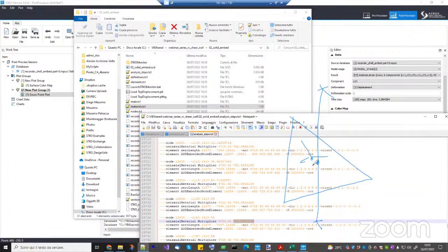Then I take this node, I create a link here, and in this link I put a uniaxial material in the axial direction. Now this uniaxial material is given as a stress versus displacement. I want to convert it into a force versus displacement. That's why I ask you for the diameter, okay? So that from the diameter I can compute the circumference. And from the mesh, I can get the tributary length on this side and tributary length on this side, okay?